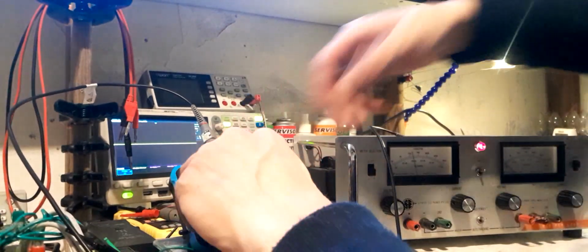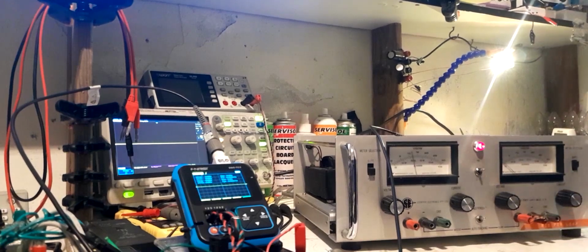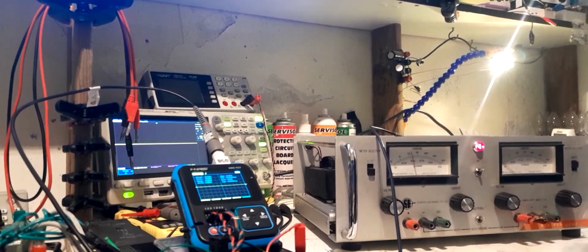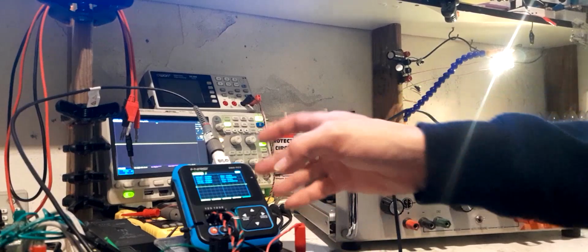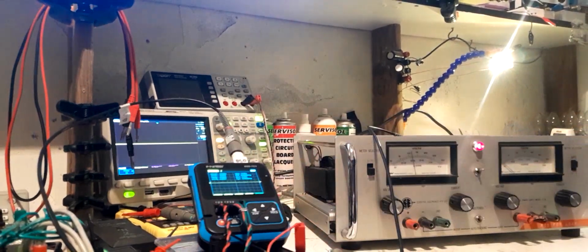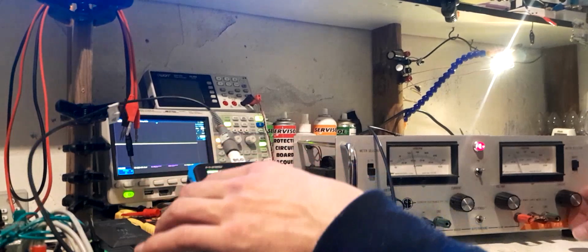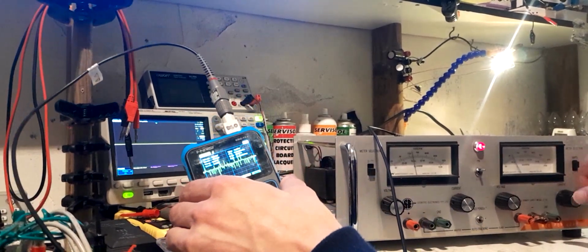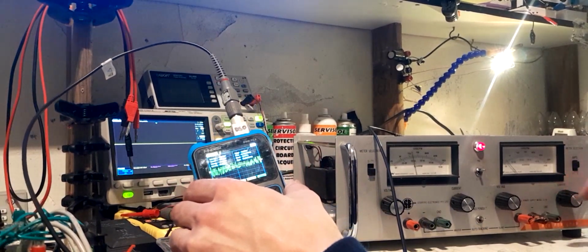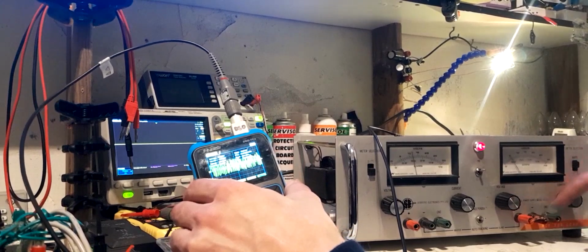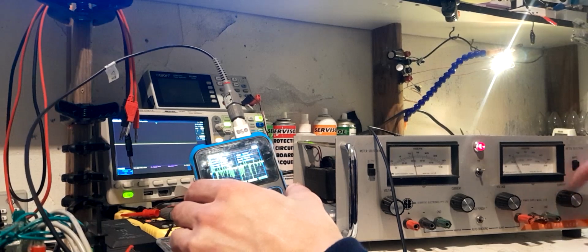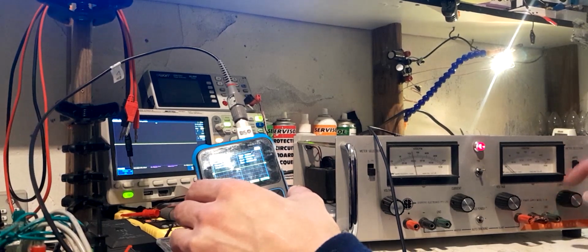I don't know, this just has higher resolution voltage wise, like volts per division, it goes down lower. One thing I will tell you is that where it says 10 millivolts a division there, that's bullshit. It actually only goes down to 20. The 10 millivolts is software driven. But anyway, you see how much more shows up on there. And this thing's only limited to a couple 100 kilohertz bandwidth or something. So anyway, we know that we do have a problem there.